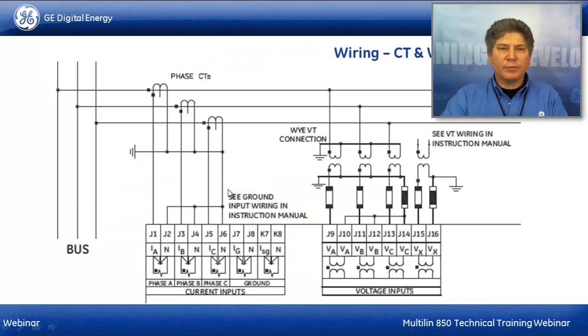All right, so slot J is housing our voltage and current inputs. We have individual contacts, with polarity markings for each one of the phases, phase A, B, and C. You can see we have polarity markings, with all neutral sides tied together, all going to ground. Same thing with the voltages. We have individual connections for the voltages. Both connections, the X1 and the X2, are coming back to the back of the relay.